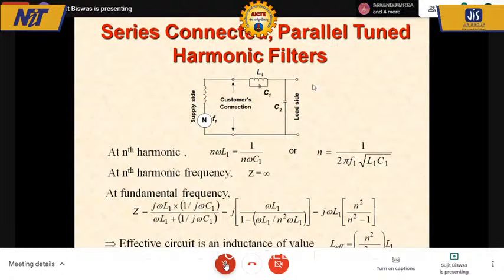We can also have series connected parallel tuned harmonic filters. We can connect L and C in parallel and tune it to the nth harmonic such that no harmonic current flows, because when I tune a parallel circuit, the impedance is almost infinitely large and no current can flow. But then I have to provide a low impedance path for the harmonics in the type of a capacitor, let us say, across the line. And therefore, the harmonics created by my load will flow within the capacitor here.